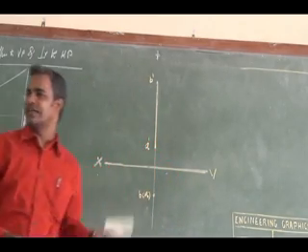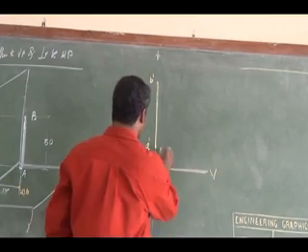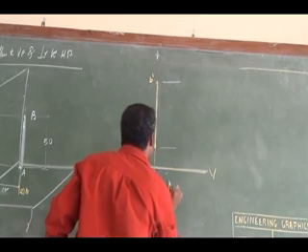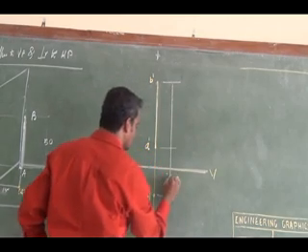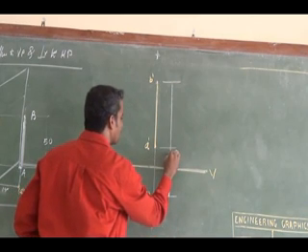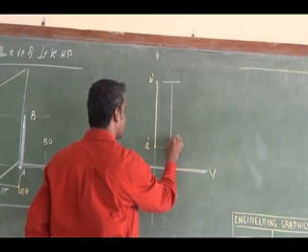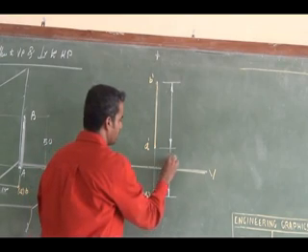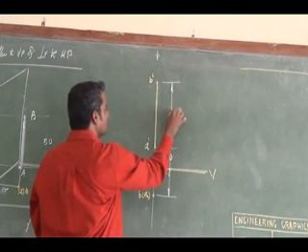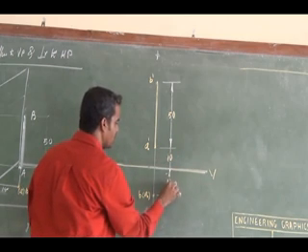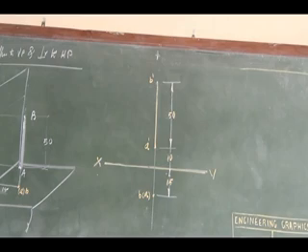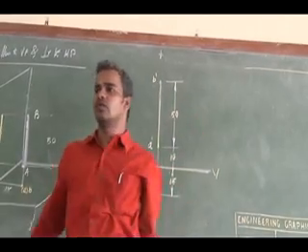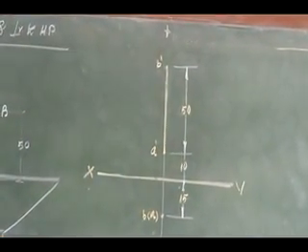What is the data given for this? That you have to dimension. So the data given for this is this and this. Dimension it all together. It's 10 mm. Right. This is 10 mm, this is 50. I can dimension it like this. But in the 10 mm gap I cannot place two arrowheads. So the outer arrowhead itself gives the meaning for dimensioning.